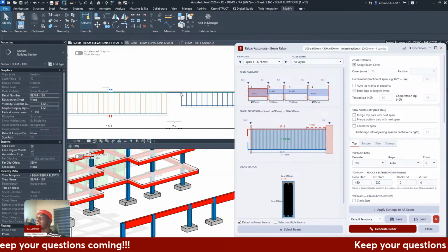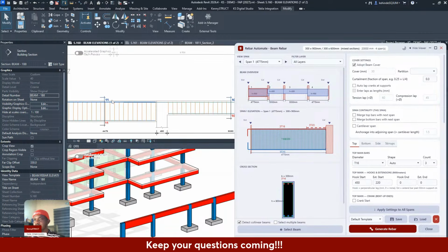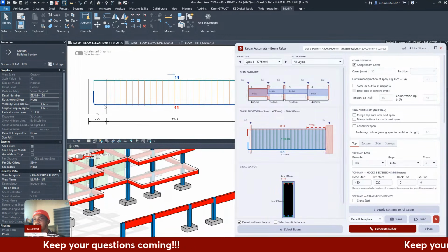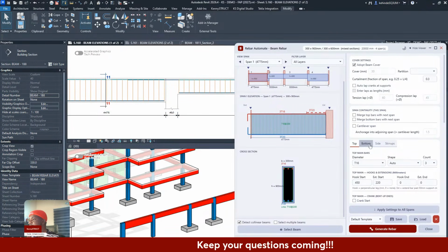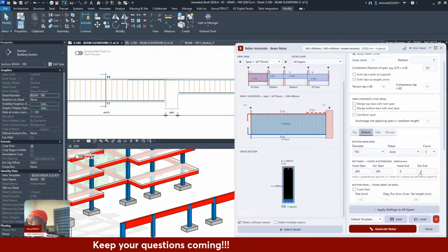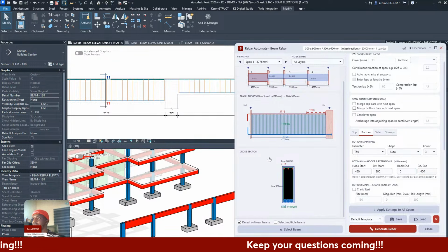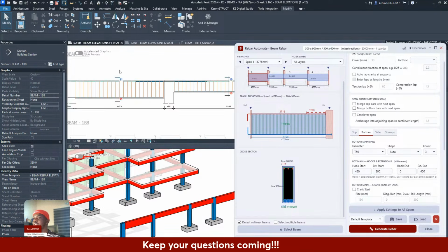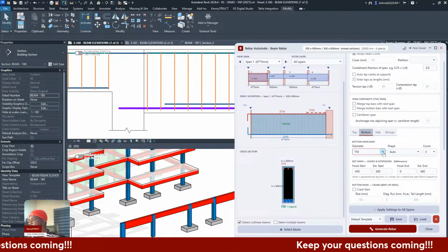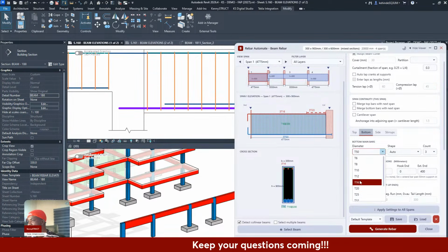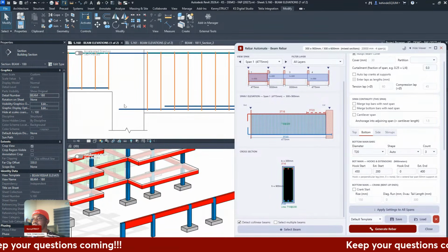Okay. All right, so I can do something here. Yeah, I have this bar. I want to extend it into the support. I just need to come to the bottom bar in this case, and then I look for the extension and I make it 400. Let's see what happens. You can see that's extended here. I think it's on this side. Oh, great, it's on this side. Oh, we picked the wrong diameter. It's saying 50 mm. Sorry, 20 mm. The next, you can see it generated.